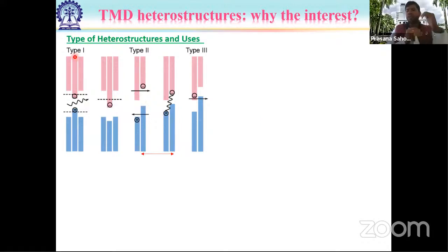Heterostructure is a combination of different heterogeneous materials. So you take one material and combine it with another, so they have distinctly different properties. Suppose your material A has a certain band gap, and you attach another material with a smaller band gap, so that you can trap carriers in a different way. This is the basic principle of many lasers and LEDs.